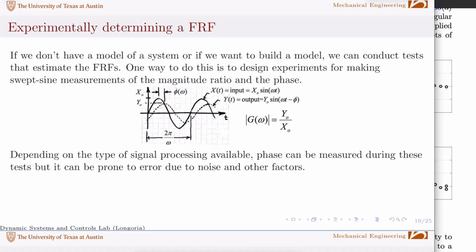I have a little figure here that illustrates a very common test. Basically the idea of frequency response is you put in a sine wave and measure the input and output and measure the amplitude ratio and the phase. That's illustrated here. I want to say two things. One is,